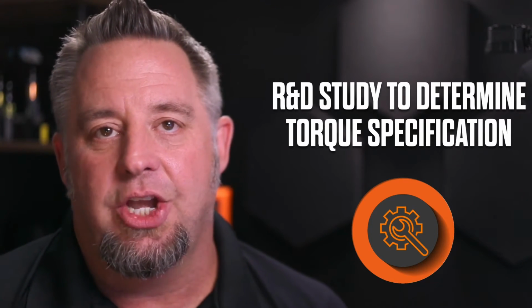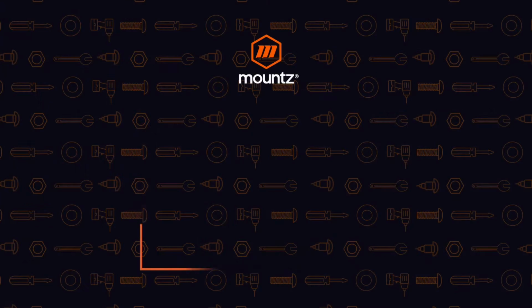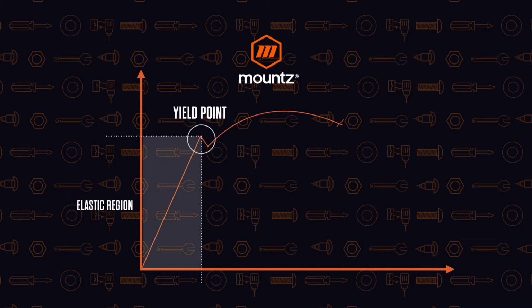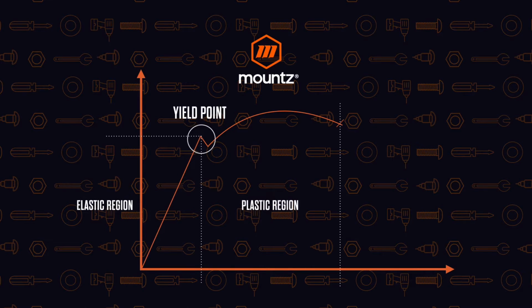If we look at using basically a yield distribution, we can help to look at what that problem is. So if we took a fastener on a joint and ran it all the way up to the yield point, or where that fastener is going to fail, we can then determine what the proof load is going to be for that particular fastener on that particular joint. And so everything in the lower left of the graph there is all of the elastic region of the fastener. At any point, if we were to back that fastener out, that fastener would then relax and come back to its original shape.